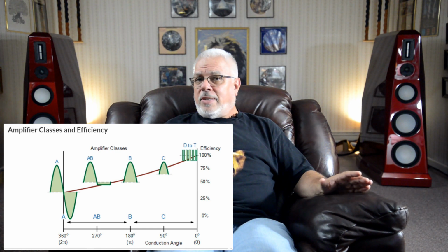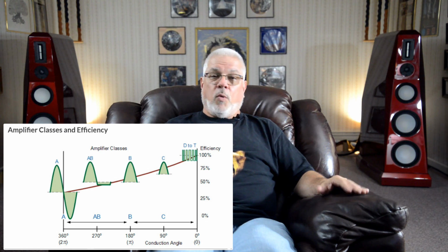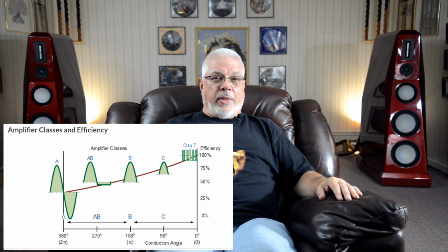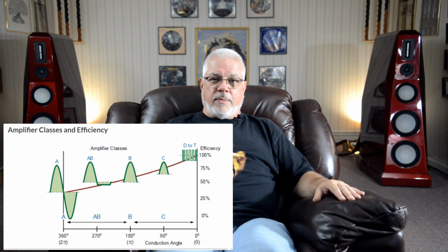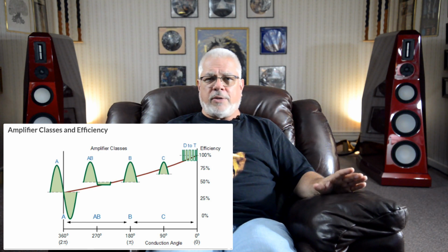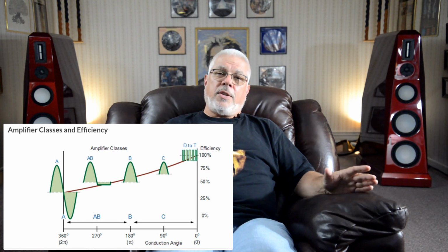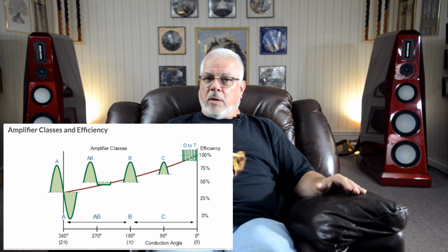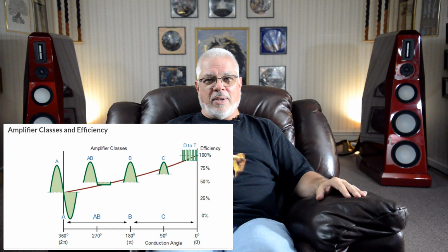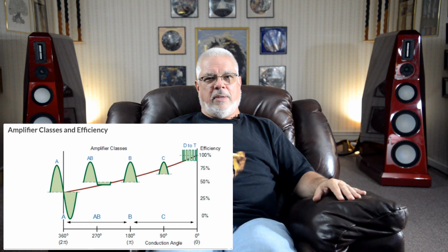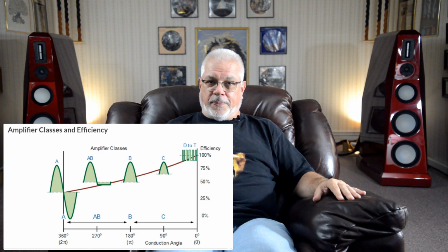With Class A designs, their simplicity is a clear strength, with some using just a single device. And because they are running at full output all the time, they exhibit no turn-on delays, have no problems with charge storage, and may offer excellent high-frequency performance and broadband tonal balance. Their disadvantages include typically higher cost per watt of output, lower overall output power, remarkably poor efficiency, most under 10% or so. They generate lots of heat, and they have reduced device lifespans.